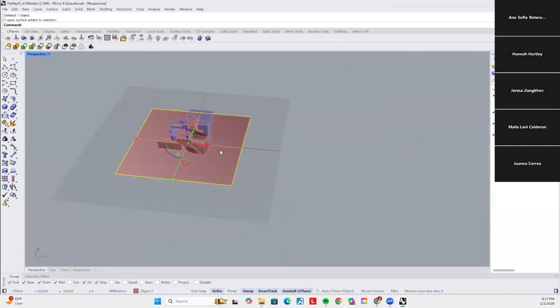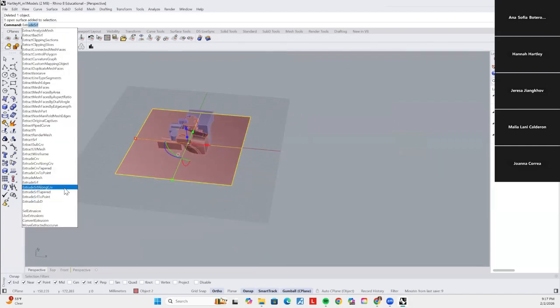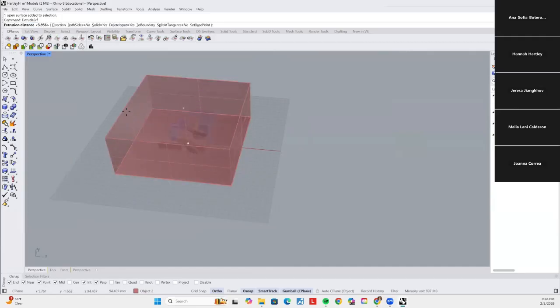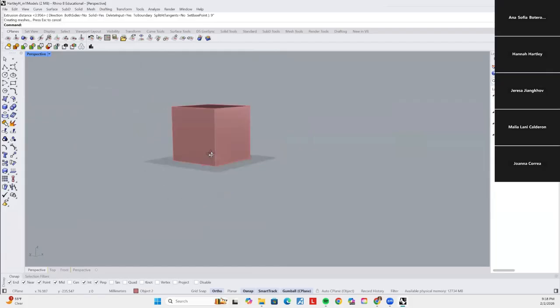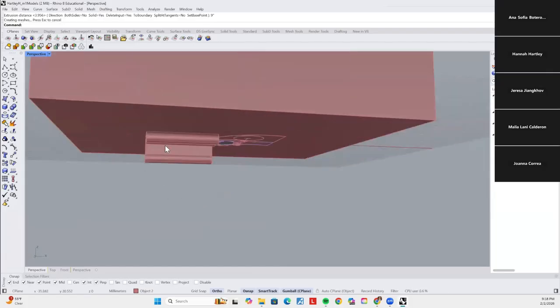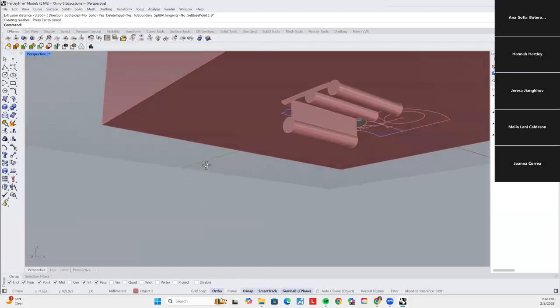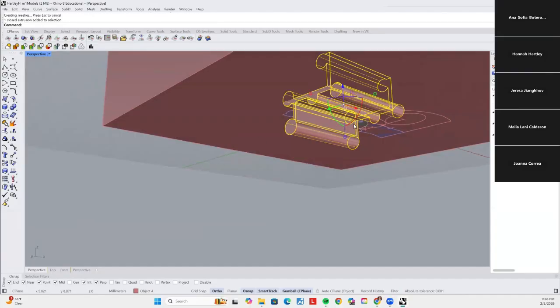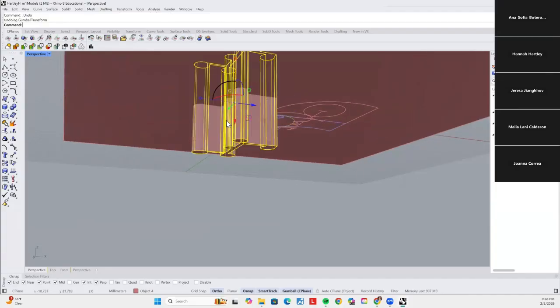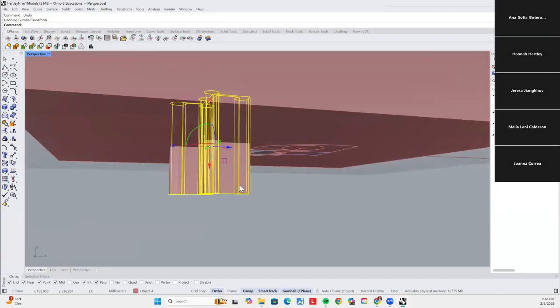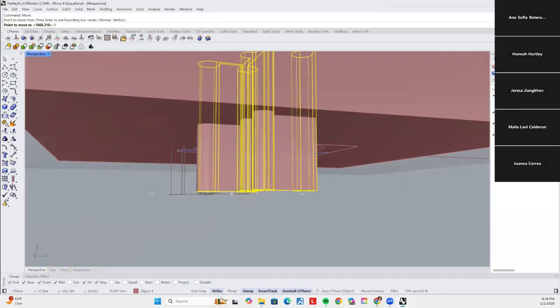So for future reference, if you guys have something crazy, like super tall, 9 inches is the max that it'll go. So this is how my 3D printed box looks. You're gonna have to rotate certain things to be flat. So I'm gonna rotate 90. Oh, it needs to be the other way. There we go. And then again, I'm gonna click move 0, 0, 0.